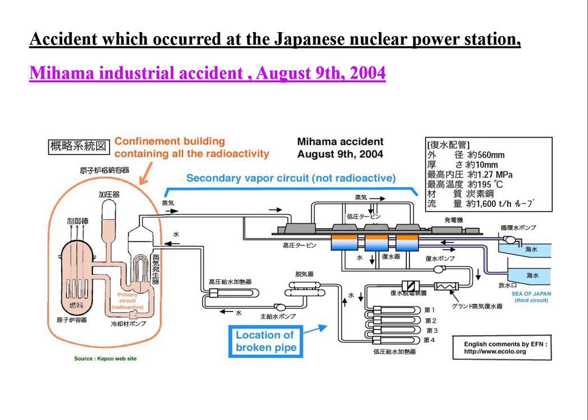Of course, thinning could happen because of corrosion or erosion or chemical action or whatever. So initially, why was this pipeline not reliable? It was not reliable because the material of the pipeline is not compatible with the media. That's why it was subjected to that wear and thinning during that period.